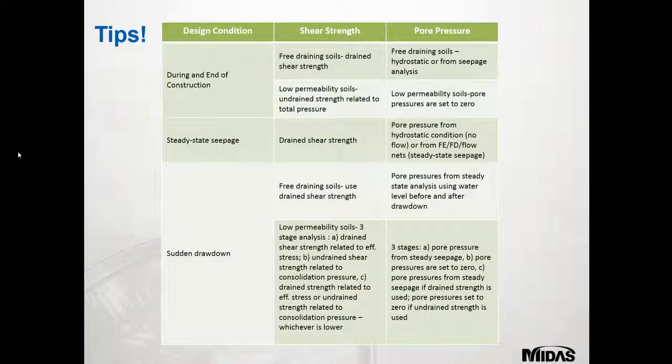So just some tips. The main problem in slope stability analysis is how to choose appropriate shear strength parameters and to account for the pore pressures. This table highlights common design situations and how to choose these parameters accordingly.